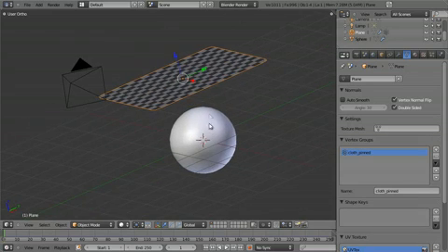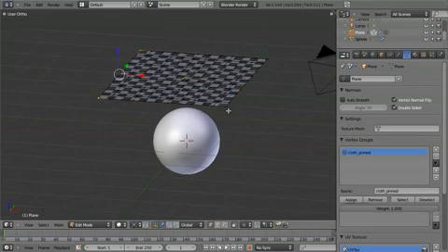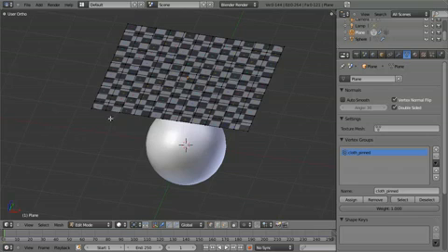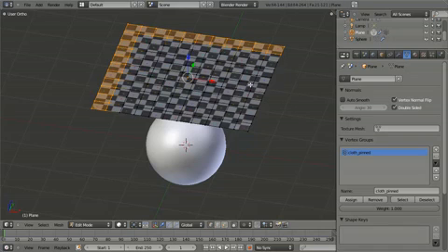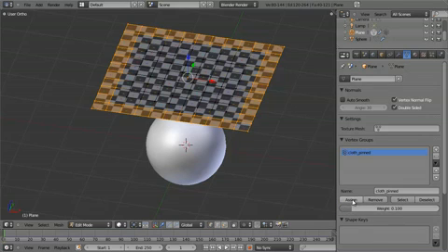Or another use for that would be, say, maybe you've got a layered material. So maybe around the edges the cloth is kind of folded back. Well, let's just go ahead and select all the edges here where maybe the cloth has been folded back on itself. Give this maybe a 0.1 weight and click assign.